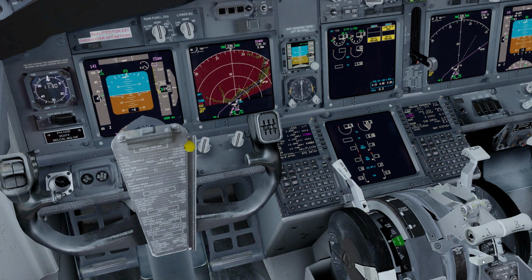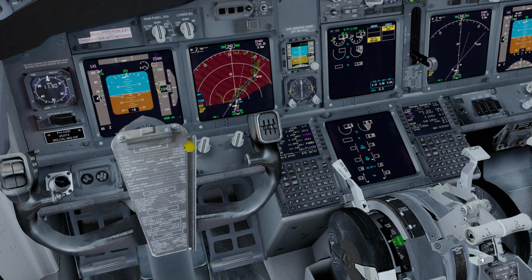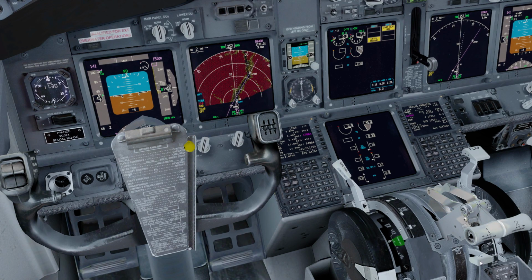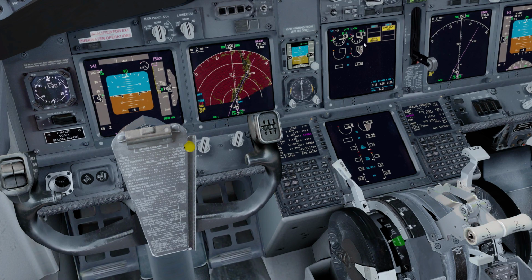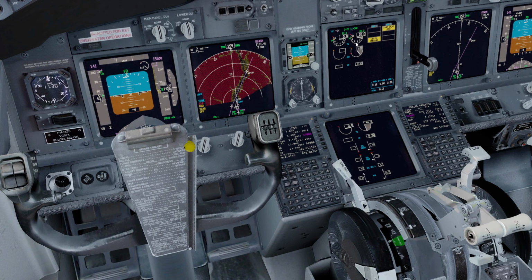You want to make sure that you keep your hand or your mouse cursor on the fuel switch, because if something happens to the engine, you can quickly cut off the fuel in order to avoid the engine startup. Monitor all the values, make sure that everything is okay, and one value is rising, EGT is rising, everything is staying within limits. We have oil temperature rising, oil pressure rising, fuel flow is coming up, and as you can hear, the engine is starting up.